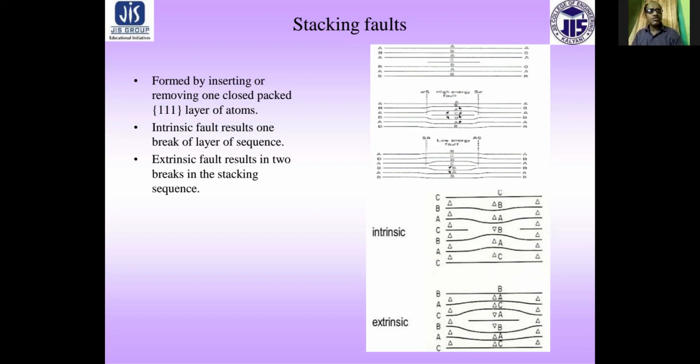Another type of structure, called hexagonal close-packed and face-centered cubic structures, is described by stacking of identical close-packed planes one over the other. The HCP structure is produced by a stacking sequence of the type AB, in which any one atom from the second plane occupies any one interstitial site of the first.